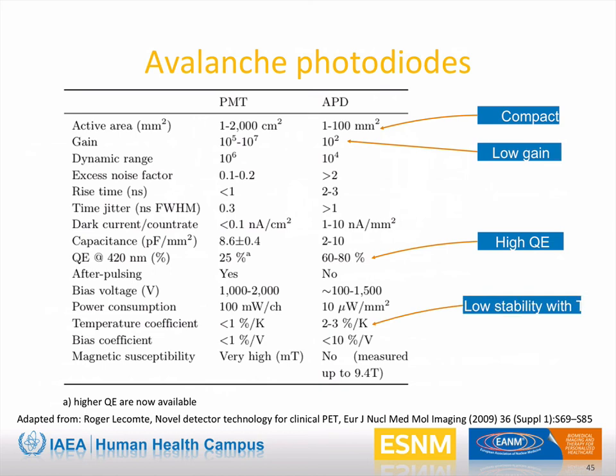The noise level of this device is dependent on the bias voltage and on the temperature. APDs are then usually connected to a cooling system to stabilize the signal, thus improving the signal-to-noise ratio. In addition, they are quite slow compared to the photomultiplier tube, and hence they are not adequate for time-of-flight PET. On the other hand, they are insensitive to magnetic fields, and thus can be used in hybrid PET-MR systems.